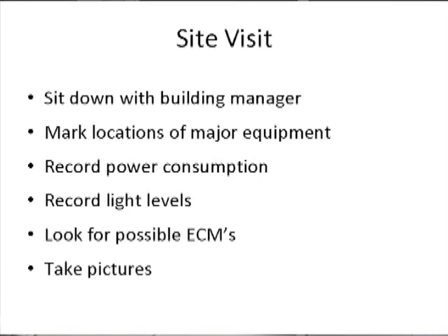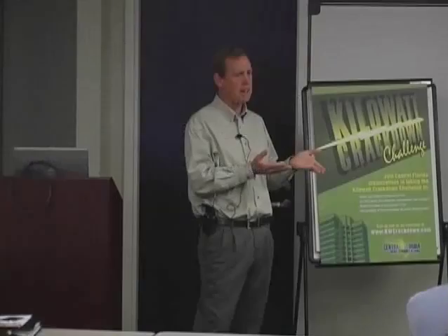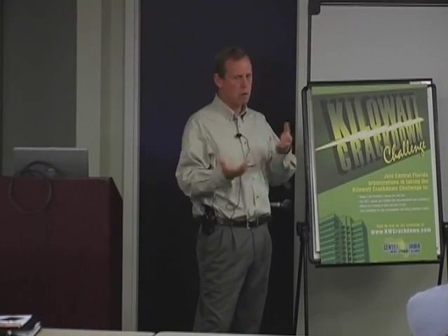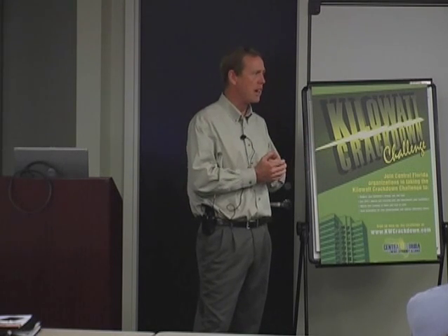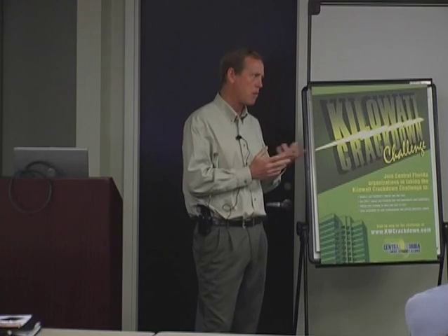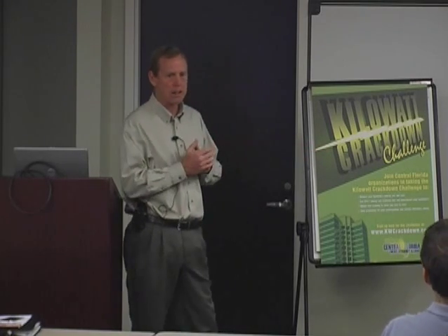So if you're in an office, you have a big range, but depending on what you're doing in the office, whether you're doing detailed accounting work, then you need maybe more light. If you're looking at a computer all day, then you need a different light level. So these guys publish all that. We compare our existing light levels with that list before we do the retrofit to make sure we don't overlight it. And we find out probably 70% of our spaces are overlit at the university.